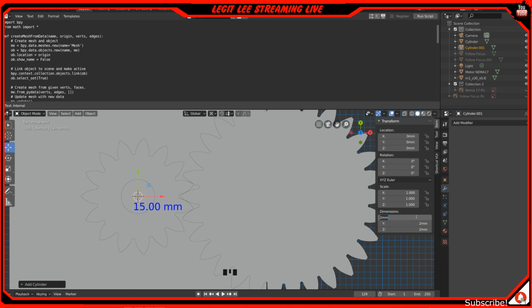And now we're going to make the hole for our cylinder, or at least for our second gear. The second gear is going to be 16 millimeters, so I'm going to put like 16.3 for this. Like I said, for that shrinkage, you're going to want to be a little bigger, just a tad, not a lot. 16.3, and then the top and bottom portion is 5 millimeters, so I'll do 5.1 or something, or 5.2. Yeah, that'll do good. 5.2.